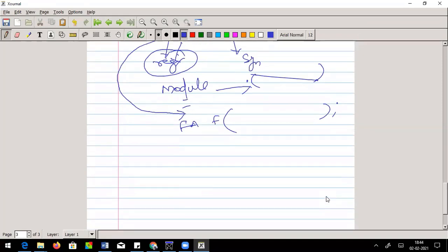After this, mainly you use two statements, that is always and the other one initial. The main difference I said yesterday, can someone recollect? What is the difference between always and initial? Come on. No answer? Initial will run only once, while always runs every time there's a change in value.